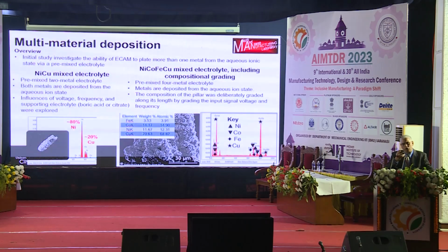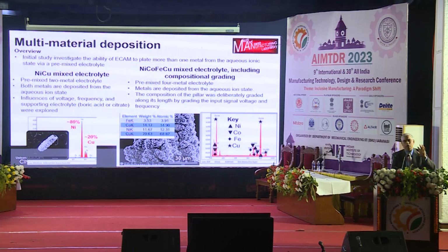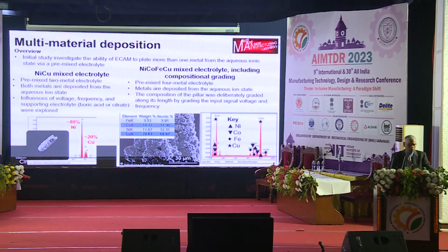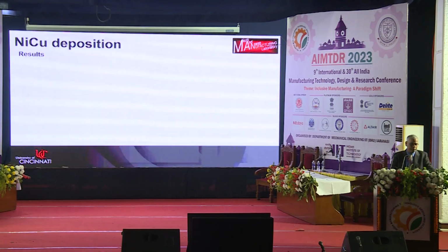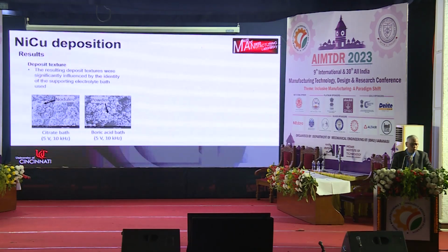Once we were successful with two materials, we tried to expand that. What you are seeing here is a four-material deposition. The same idea: have the ions, whatever you want to deposit, in the form of a salt solution in the bath, and do the deposition. So quickly look at this.